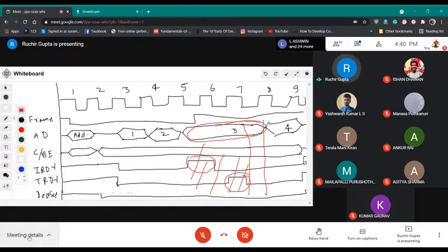So the read operation starts the same way, and first two words are transferred. And when target sends the third word, at that time initiator is not able to receive that. So that's the problem, right? It does not receive, and the target maintains the third word for longer duration. Are you getting my point? Are you guys able to understand this?